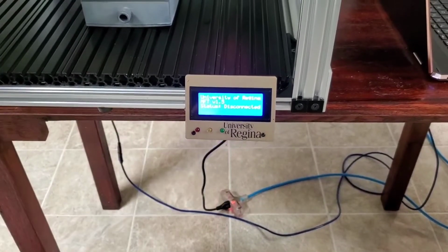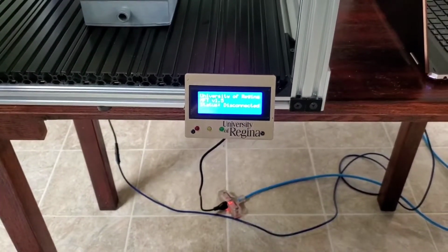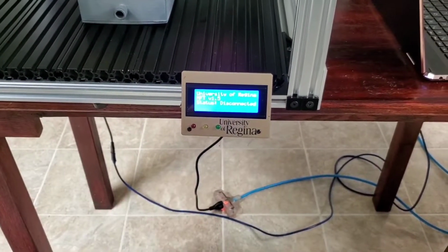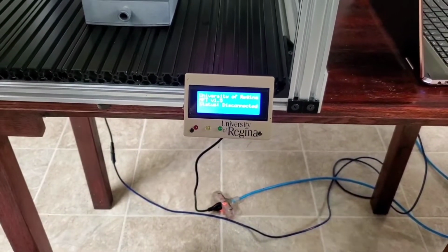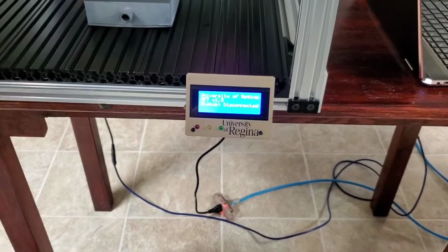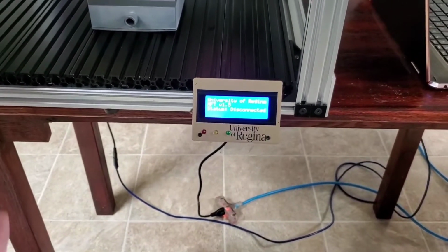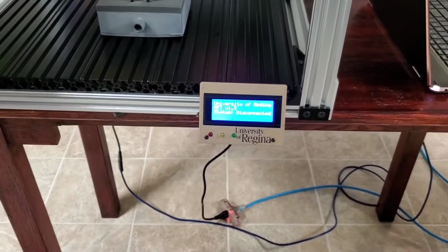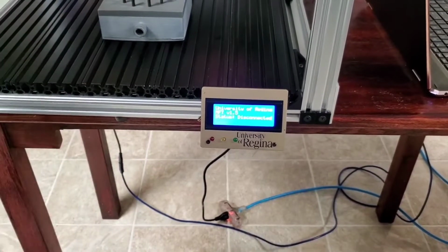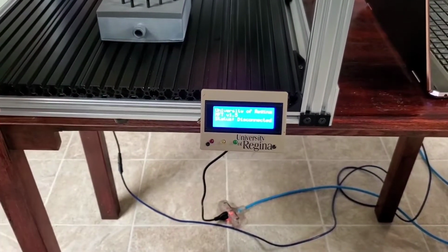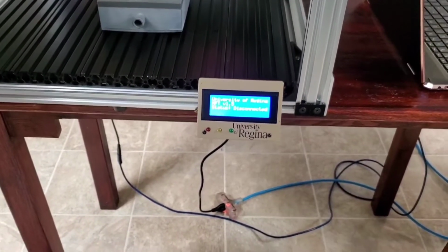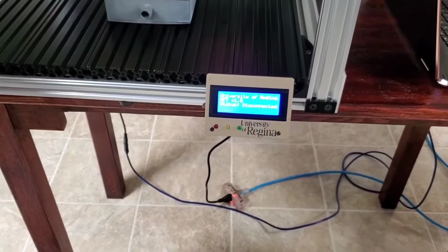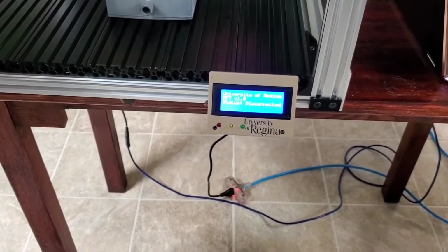Our second line is the version of the machine, as well as its shorthand name of MFT. Our third line is our status. So that'll update when we're moving phi, when we're moving X, moving Y, homing, all those situations. And finally, the fourth line only occurs when we experience an error. Such errors include a bad G-code command, or repeated bad G-code commands, or hitting a limit switch, or being unable to home the phi axis, and so on.